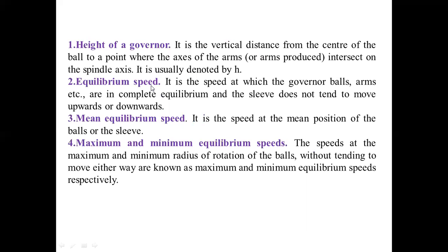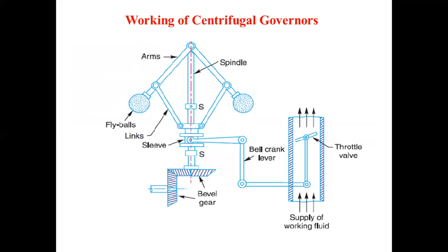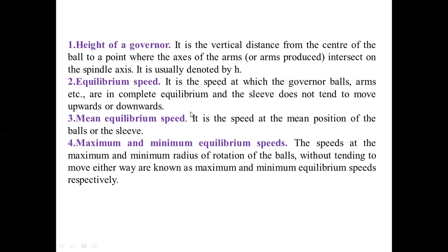The sleeve, arms and balls rotate at a constant speed, and the sleeve does not tend to move upward or downward at the equilibrium speed.